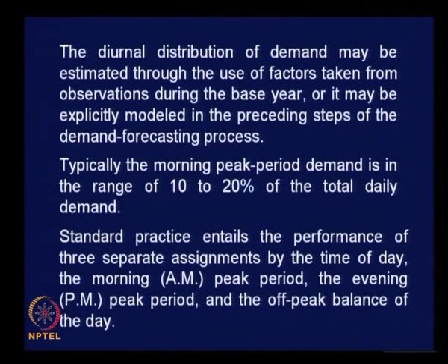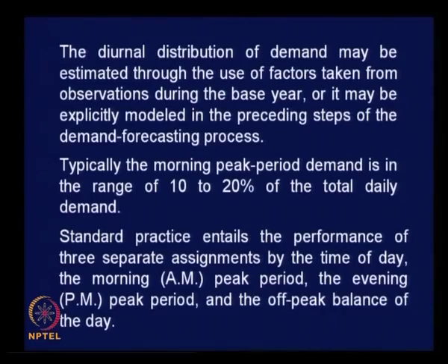You just quantify the demand for AM peak, do the traffic assignment, then PM peak, assign the traffic and visualize the traffic scenario, then non peak period, you just quantify the demand and then assign and visualize the traffic flow, right, which is similar to the desired setting for traffic signals.